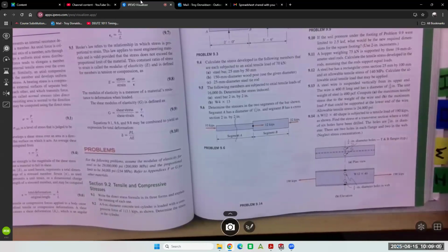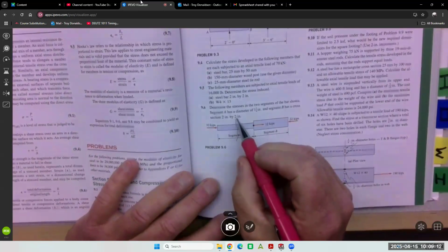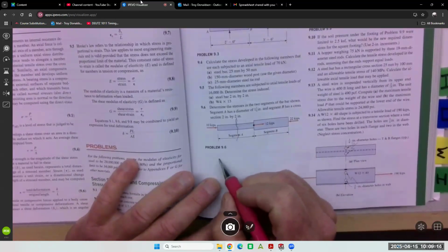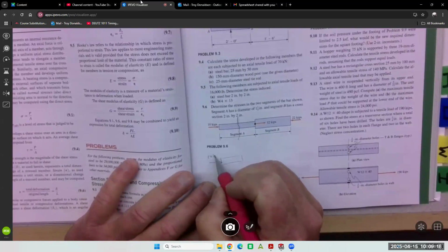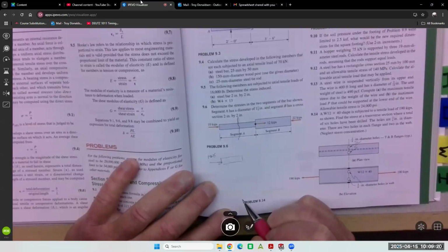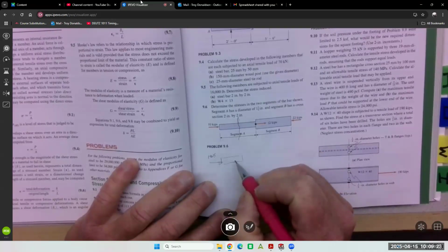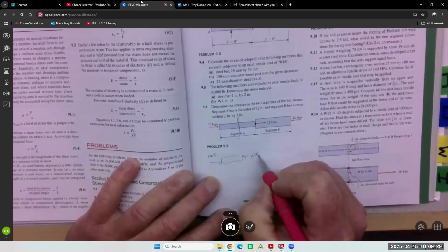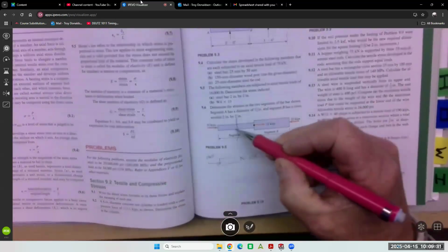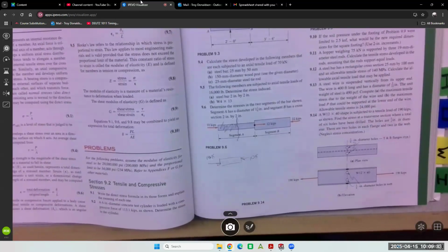That's what statics taught us. So if I cut this thing right through here and I draw the left side, it looks like this, right? Cut it here, draw the left side, it looks like that. For me to put it in equilibrium, I got to do this. That's this piece right here. Agreed? So that piece has a 10 kip compressive load on it.